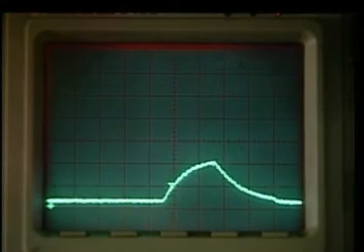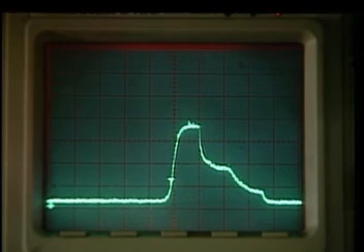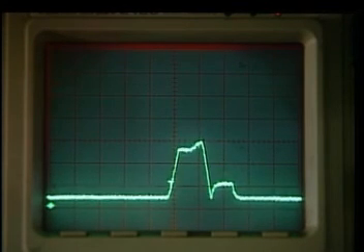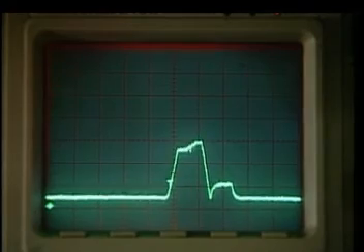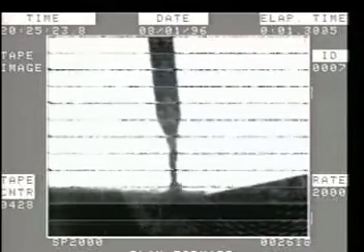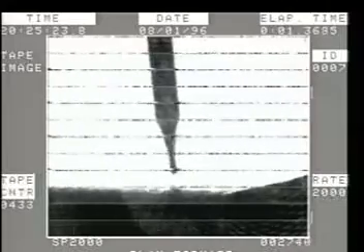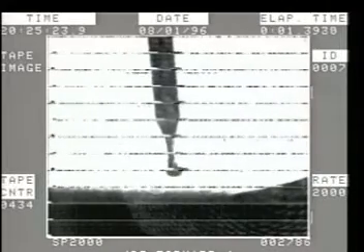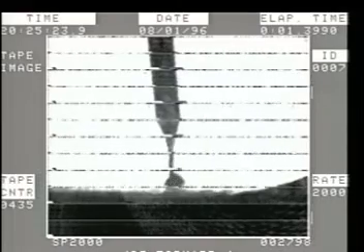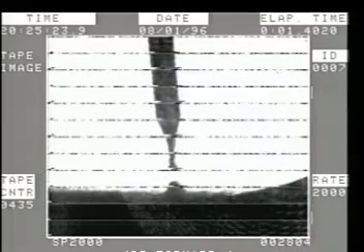Waveform control technology controls every aspect of the output waveform. First, a high-speed control delivers the ideal instantaneous welding output. Each weld is made up of individual droplets of weld metal. The high-speed control regulates the development and transfer of each droplet. The second control, the slower speed control, adapts the wave shape to maintain the proper arc length.